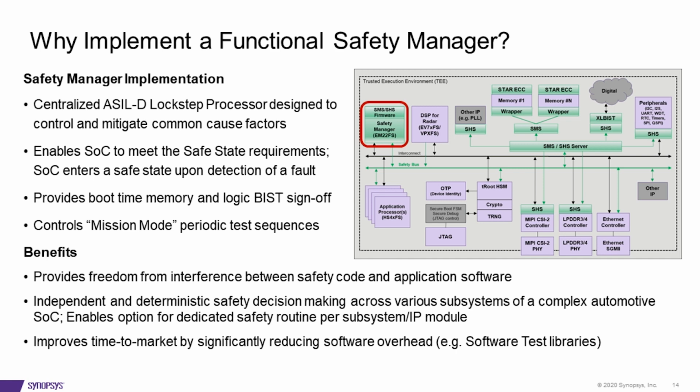So, at a high level, why would a customer or an SoC implementation team want to integrate a functional safety manager? As I said before, the idea is to have an ASIL D compliant dual-core lockstep processor that manages all the safety escalations. So it allows freedom from interference between the safety code and the application code. It provides a mechanism for independent and deterministic safety decision making.